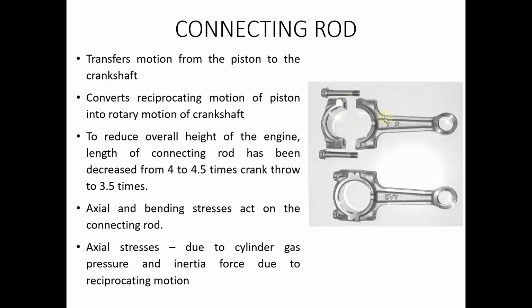So this connecting rod transfers the motion of the piston to the crankshaft, and the length of the connecting rod has now been reduced from 4 to 4.5 times the crank throw to 3.5 times, in order to reduce the overall height of the engine.